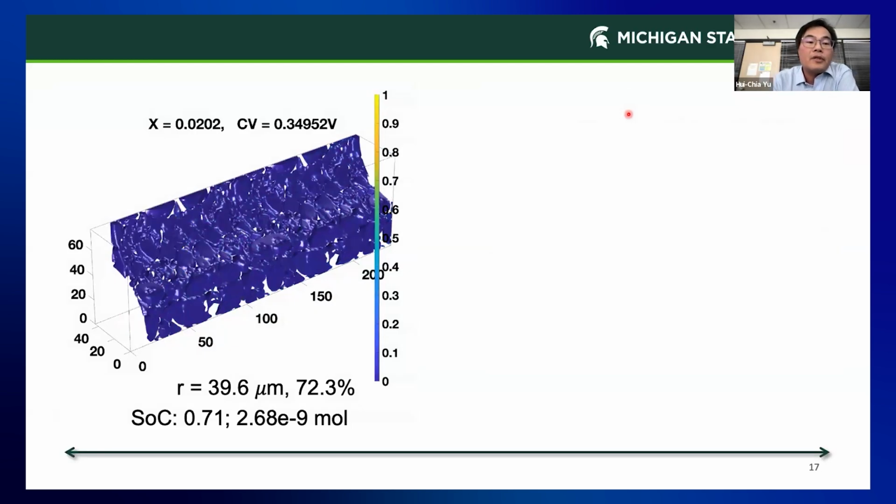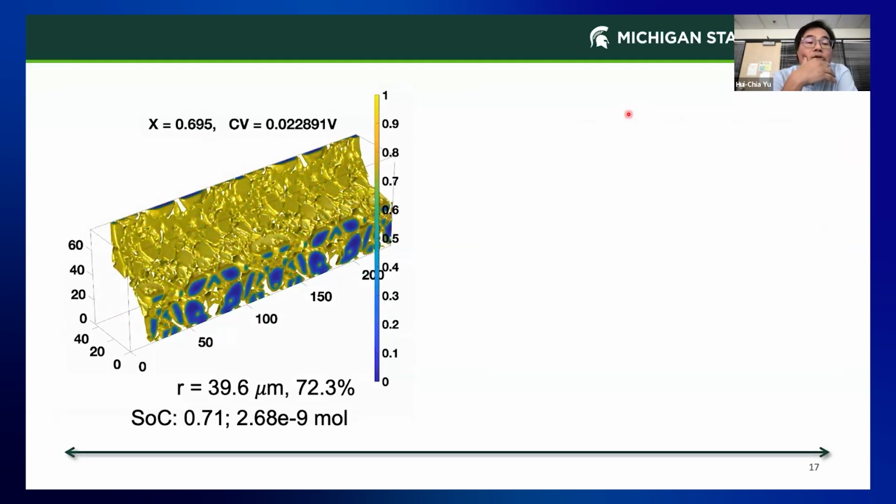And here is an extreme case. You have a very wide tunnel. And yeah, you can use much more of the electrode, and you are reaching a utilization ratio of almost 70% of your entire electrode. But you probably already noticed, right? When you have a larger tunnel, you use more of your electrode, but you are losing your materials.